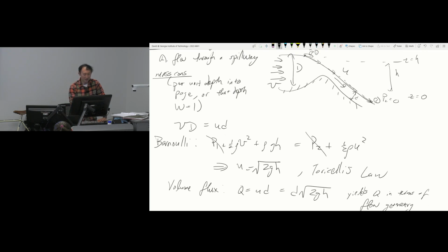So you don't have any things like this is going to be a weird homework. In all these homeworks, anytime you have a solid boundary, you still have a velocity vector right next to it, because the Reynolds numbers are so low that the boundary layer basically doesn't exist, and we just flow easily past boundaries. If you don't have viscosity, boundaries don't really affect you anymore.